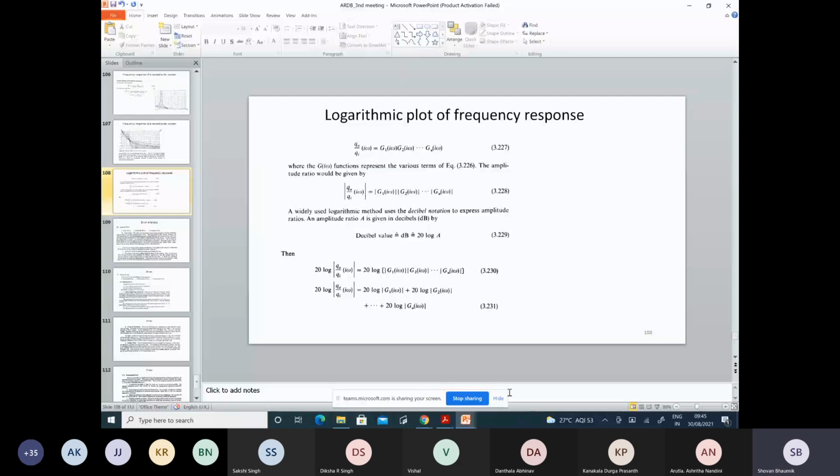And by doing so, if you plot the Bode plot, and from there you can identify the corner frequencies and the slope of the curve, you can calculate the transfer function. Sometimes calculation of the transfer function is very difficult if you take a very long frequency range.